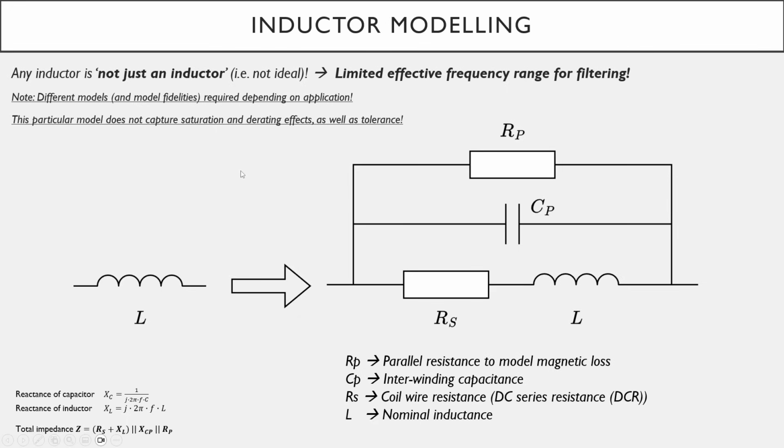For instance, if we're going to the RF domain, we are working at much higher frequencies. The frequency domain performance or frequency response of an inductor becomes more and more critical to be able to model to make sure that our circuits work as intended. It turns out that any inductor is not just an inductor, it's not just this ideal circuit element, and you might want to represent your inductor by a different model, and I've shown one of these types of models as an equivalent circuit on the right-hand side. Keep in mind there are different models and different model fidelities required depending on the application.